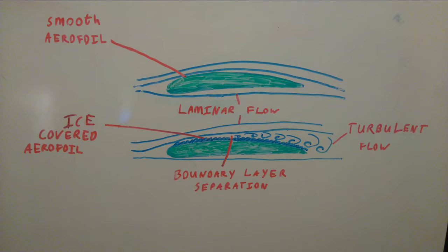Although this may only seem relevant to those deciding on the surface material of the plane, ice can form on the plane during flight, thereby increasing skin friction drag. Ice can have detrimental effects on a wing, as it can cause a wing to stall at a lower angle of attack. This is caused by the rough surface forcing the boundary layer to separate much earlier on.